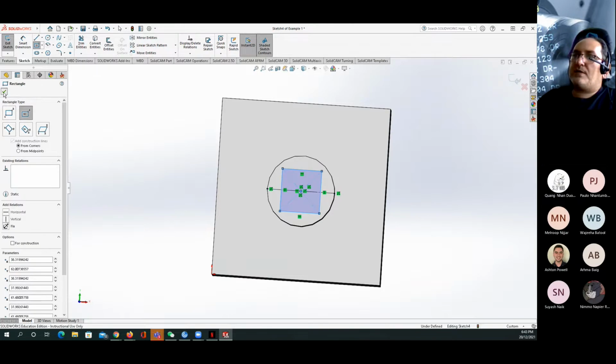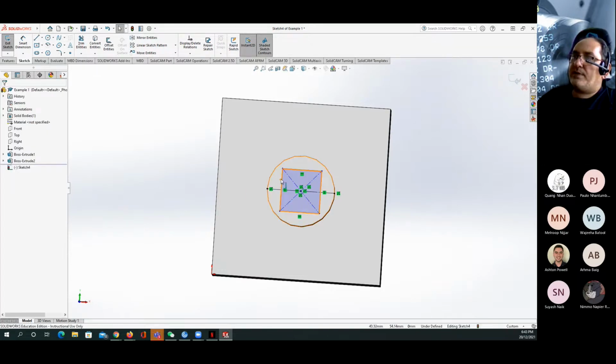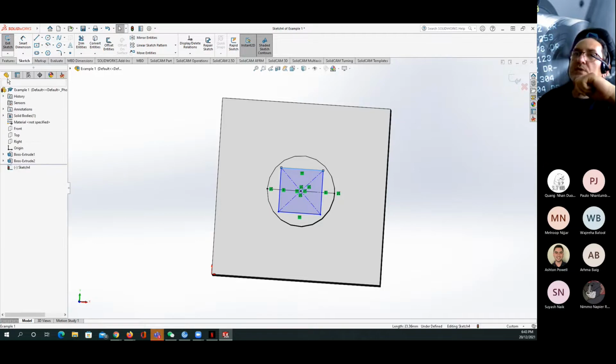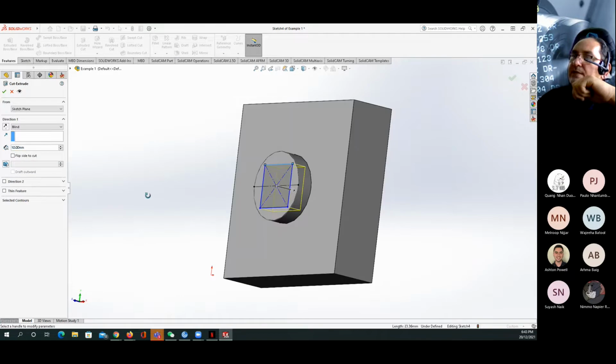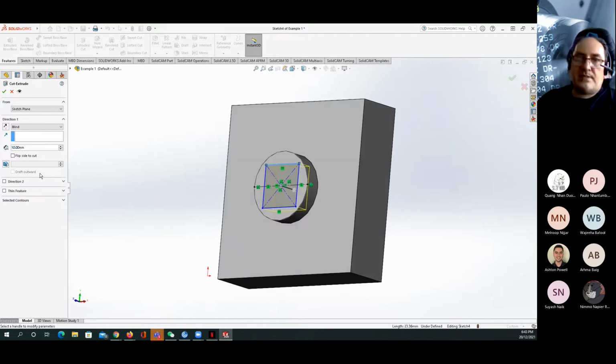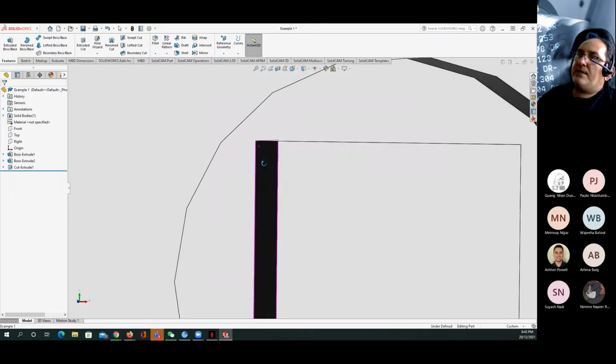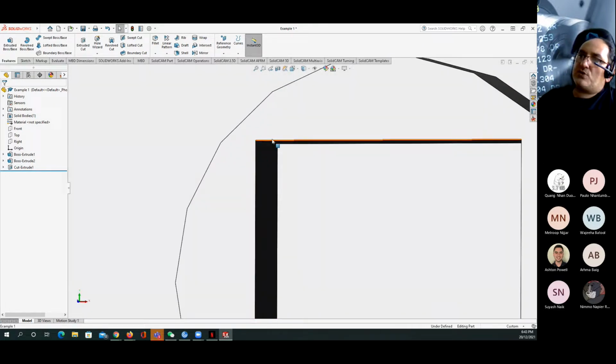Okay, so once again, if I would like to cut anything with sharp edges in the milling operation, it's not going to work. So we need to change that to have a fillet side. So this will be the square shape, and that will be the pocket we're going to have. I'm going to take it down by 10 millimeters. Say okay. To cut such a pocket, it's going to be impossible to have the corner on this side. So this needs to be changed into a fillet.